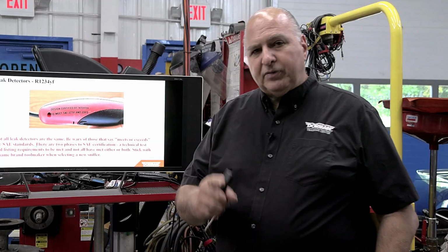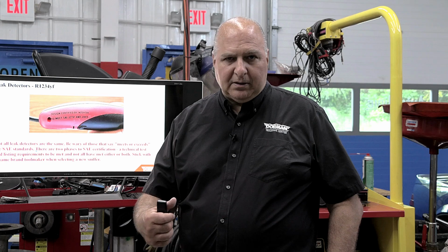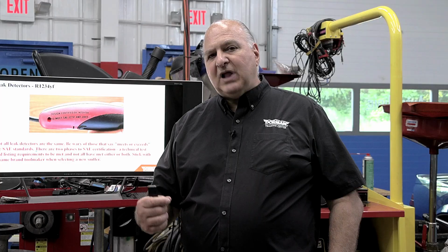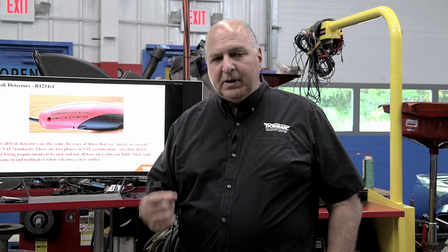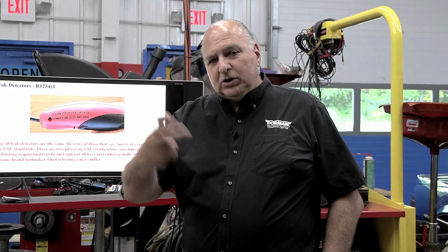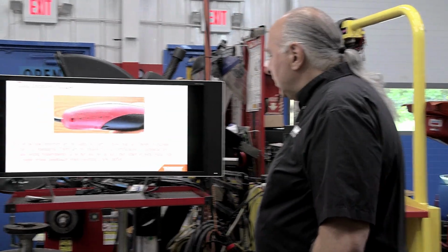It is mandatory to put the fan on low, air coming out of the panels to the floor, and leave this thing there for 5 minutes. Okay, it is a DOT requirement, because that refrigerant is flammable. Yes, you heard me, 1234yf is flammable, and there's only been a few cases of any fires, but do you want to be the person where that car goes on fire? You worked on it? You know those law firms you see on TV, they're just waiting to sue someone. And you don't want to get sued, do you, right? So do it right, cover your butt.